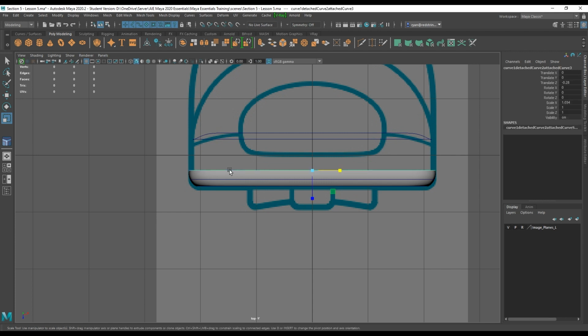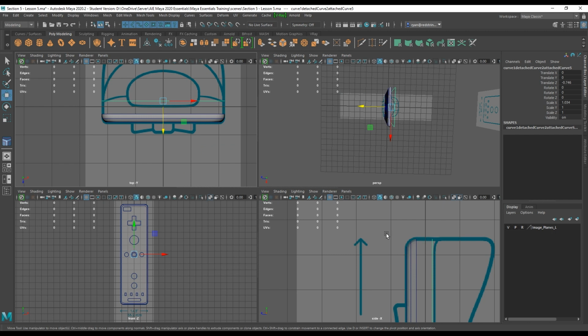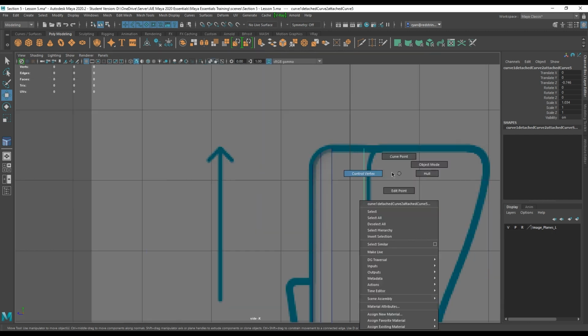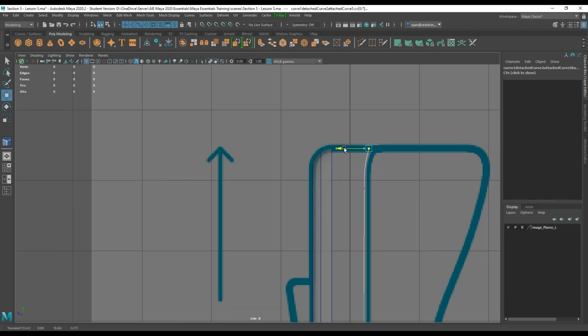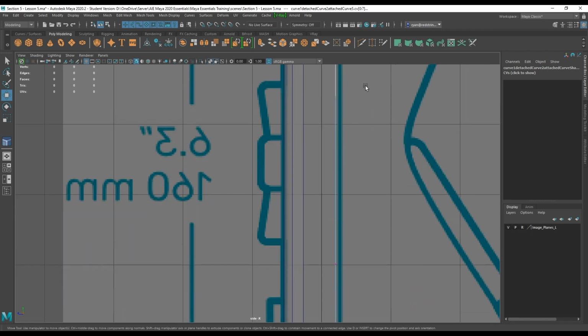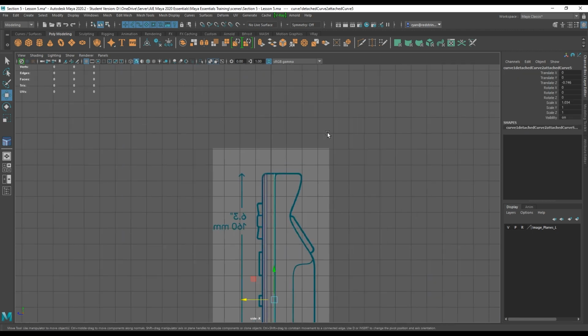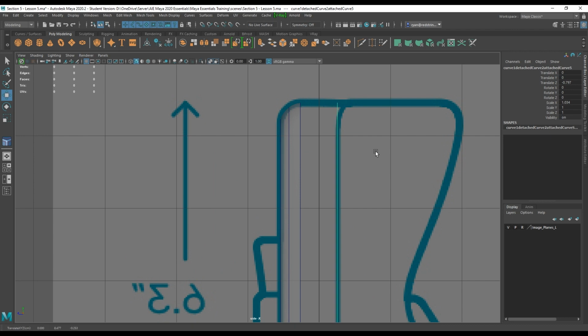Now I'm going to grab this curve and delete this guy, because now that I've scaled them out, this curve doesn't match the previous one. So I'm going to select this curve again. You select the surface, Control D, move it into space like so. Then I would like to start pulling it in the side view to match up to what we have.